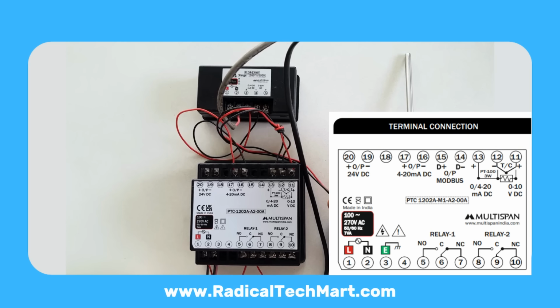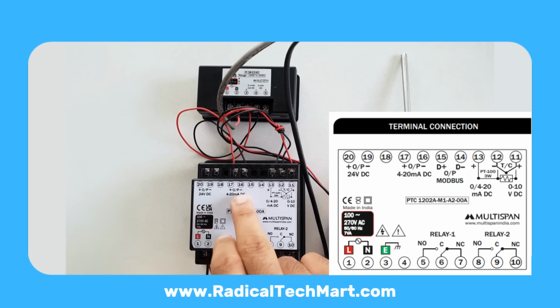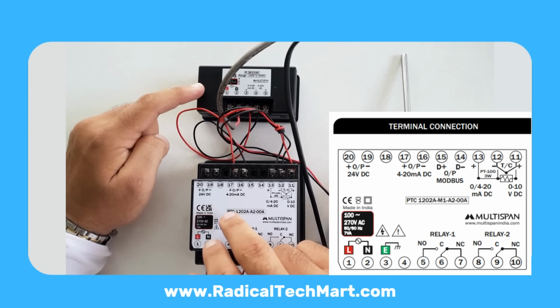RTD, PT100 wiring: red, plus, to terminal 11. Black, to 12 and 13, the two light-colored leads. Some PT100s come as one red and two white leads. In that case, red to 11, whites to 12 and 13. Thermocouple, typically 2-wire, 11 and 12. 4 to 20 mA input: 13 is plus, 12 is minus. 0 to 10 volts input: 11 is plus, 12 is minus.